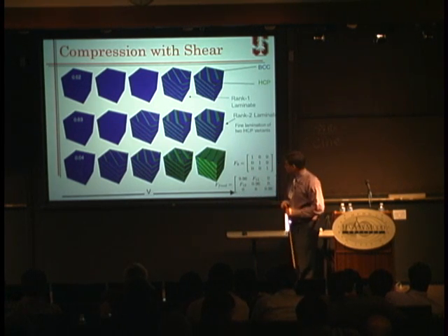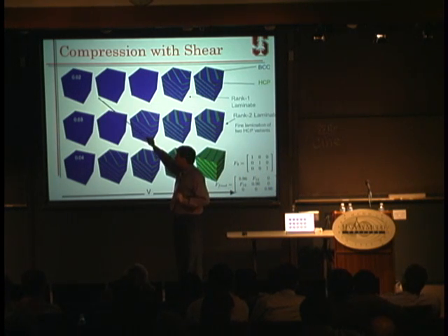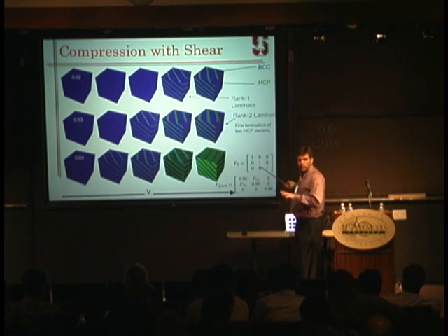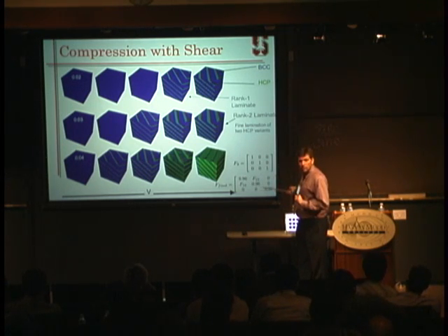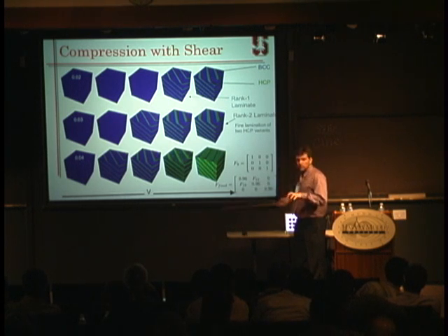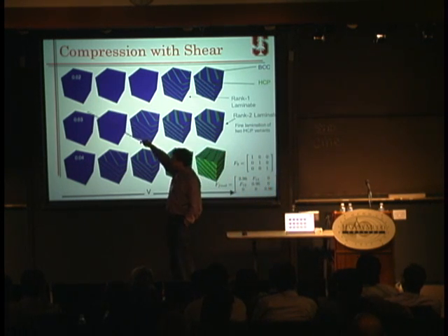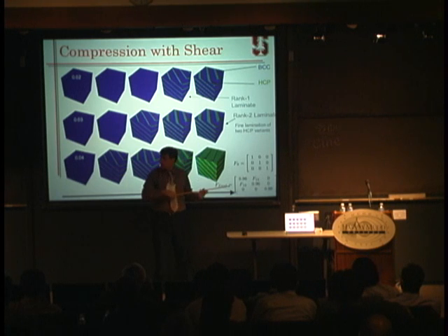So let me show you the results. Now, here we have a BCC sample, which is in blue. And we start with the deformation, an affine deformation of the boundary, which is the identity, no stress. And we push it such that we uniformly compress it, and add some terms that will distort it, okay? And we change the value of f12 in these simulations, okay? So here we have f12 equal to 0.02, 0.03, and 0.04, very little. So you start loading, you go from f to f final linearly, okay? You just interpolate these two things linearly.